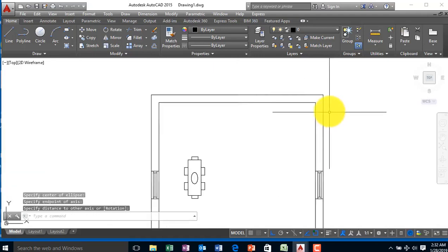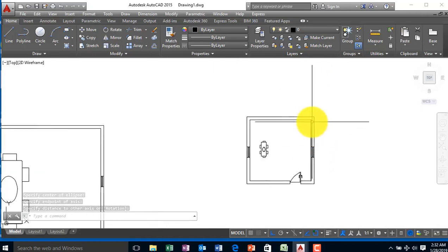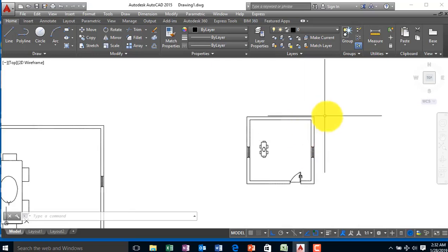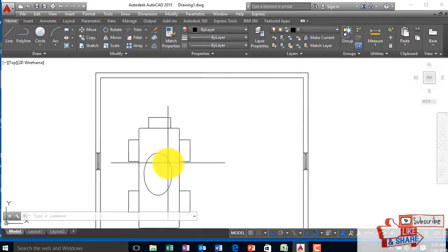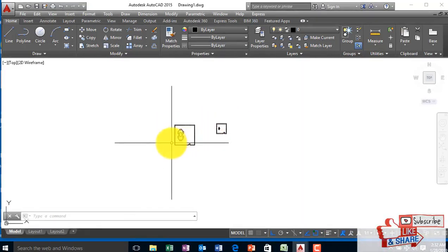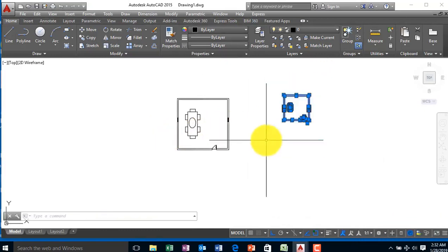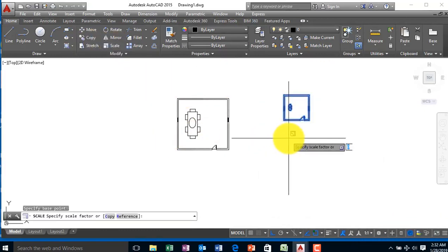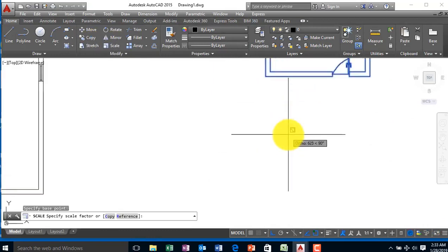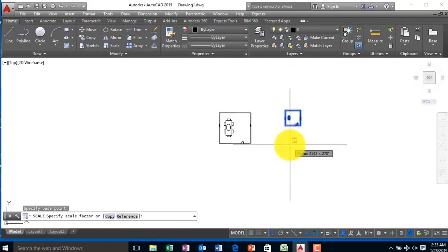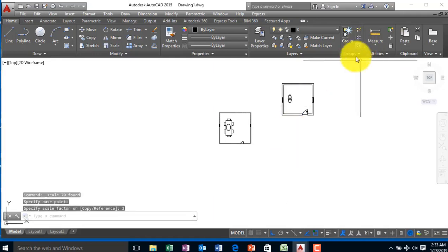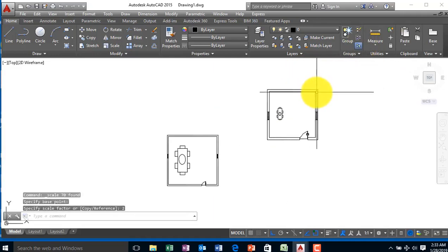So quickly, you see that we'll be able to achieve a lot today. And without wasting much of our time, I would like to bring this tutorial to a close. And in our subsequent tutorials, we'll be seeing how to make the elevations. If you compare these two, you will discover that they are the same. If I want it to be about this size, I can still come here and scale it. When you click on it, then maybe let's say I want it times 2. Now enter maybe 2, click on enter, discover that it has increased in size. That's another use of scale.